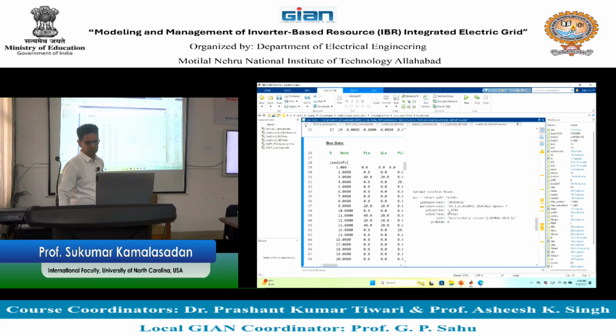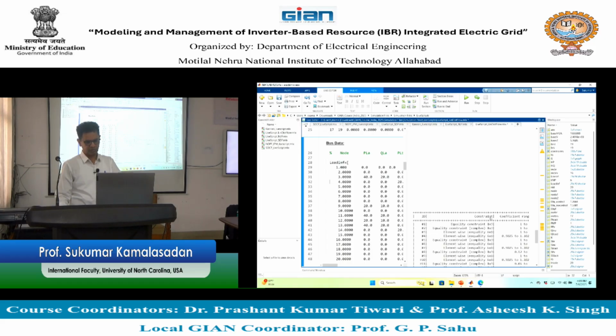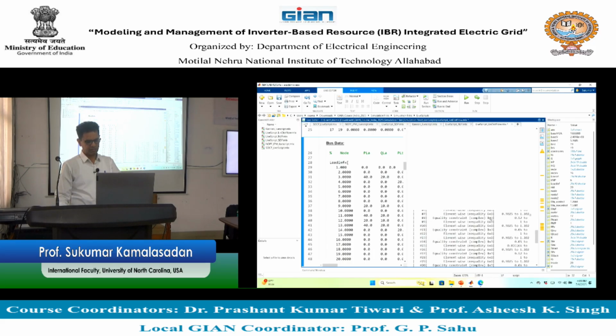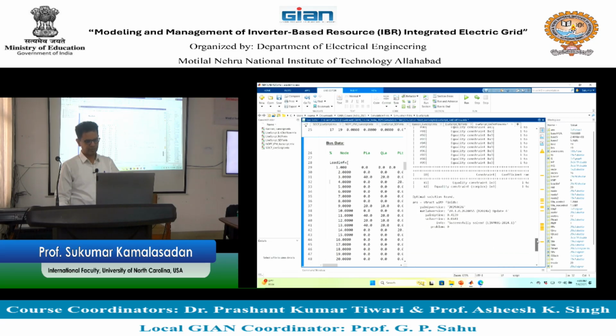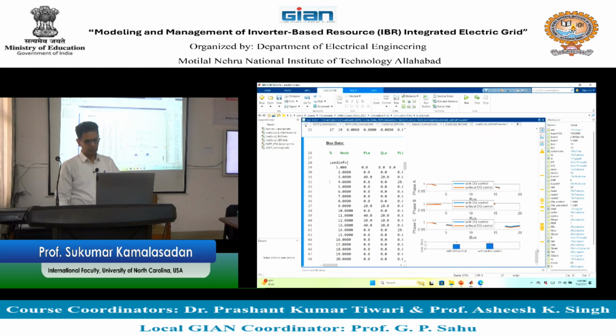This is the solve time. This is actually the time that is taken by LMIP, and this one is giving that it successfully solved with a solver called linear programming, and the element-wise distribution of constraints, how the constraints are taken, and the coefficient rating associated with that. These are some metrics for the OPF, and you will be able to see the performance by looking at the voltage profile for all three phases for the 20 bus, with and without the optimization, and comparing.